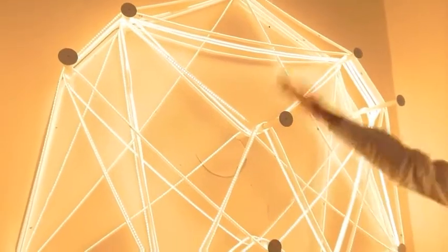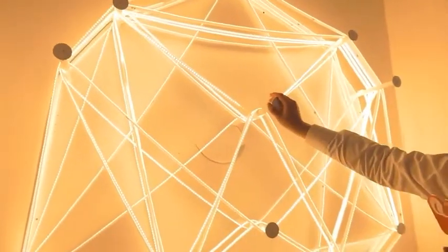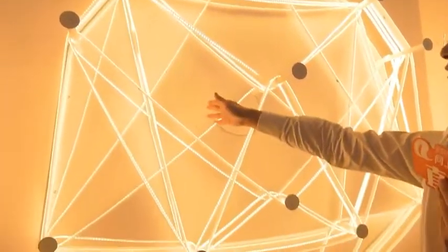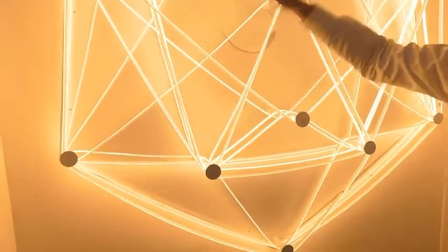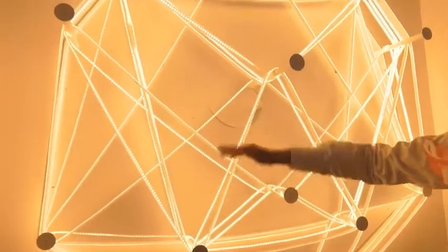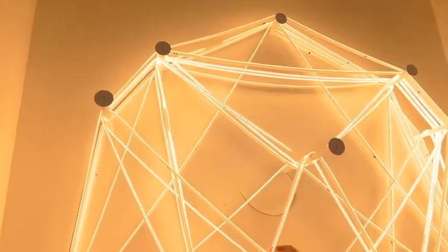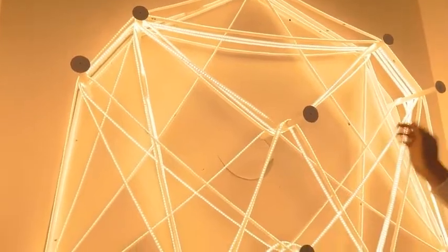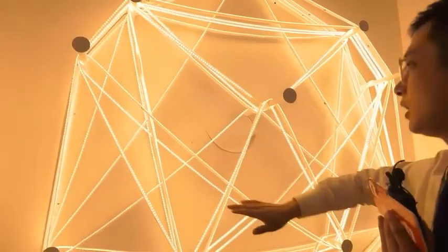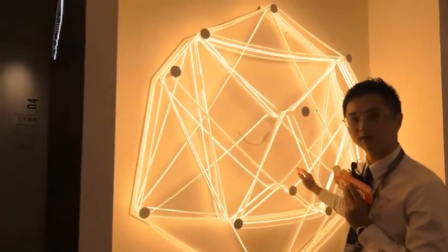You can see it's so long, and maybe you're thinking it's 220 volt, but actually it's 48 volts. 48 volt, low voltage strip. And why is it so long? Because we have a different design. We have a constant current IC to keep the current stable.